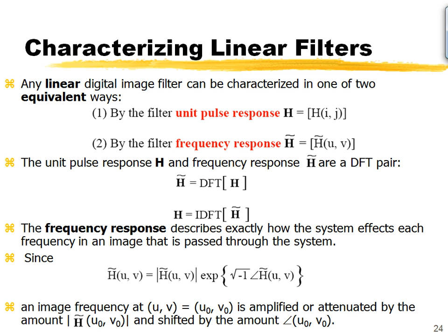Now, remember, we can design filters either in space domain or in frequency domain, right? It's the same, they are linear transforms, so they're invertible. So it doesn't matter which domain I design a filter in. The choice is really dependent on in which domain we can express the properties of the filter that we wish to design.